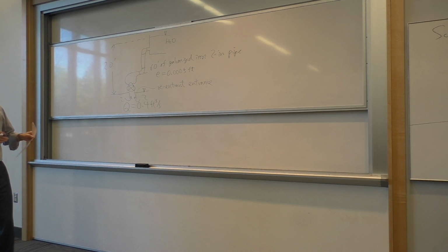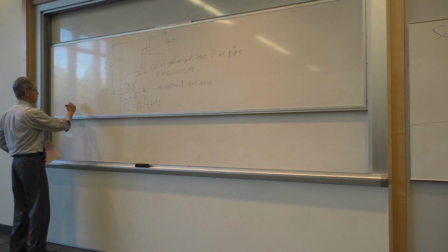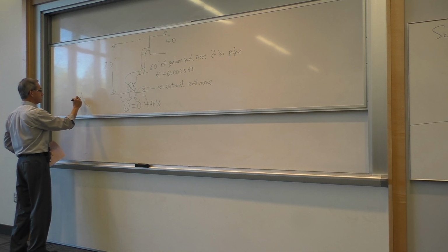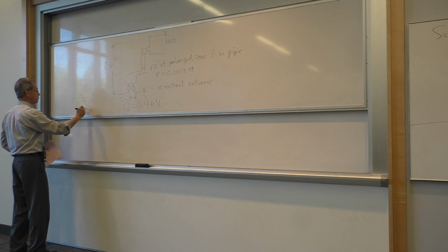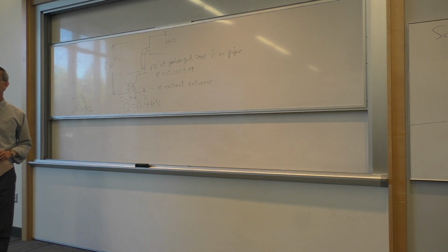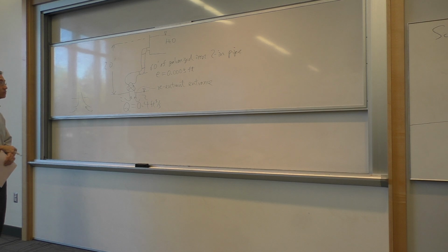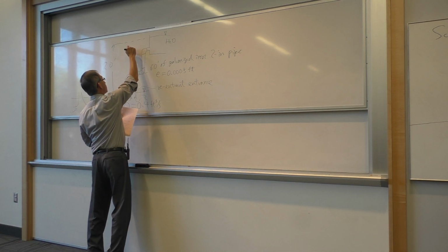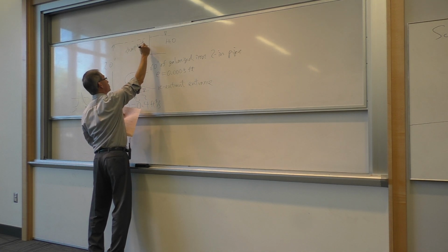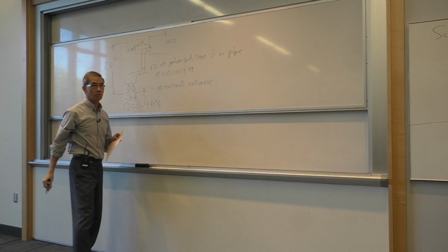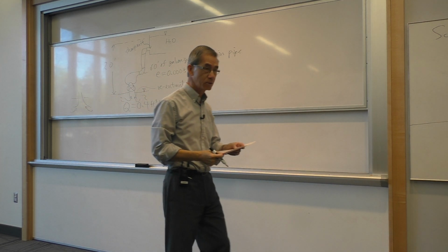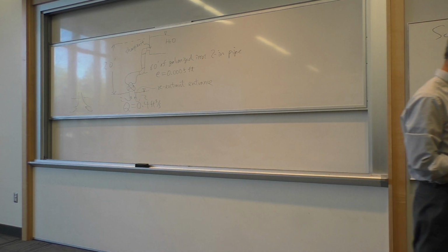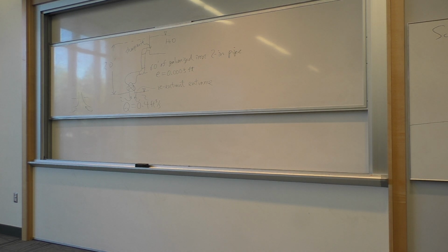You can imagine if I have a very smooth bell mouth, instead of a sharp intake, I have something like this. It may be easier for the water to get sucked into the pump, but we have a very different device. It's just a sharp pipe deep into the water. The exit also has no attempt to smooth the exiting flow. It's just a pipe dumping into a tank at an open angle. We call it a sharp exit.